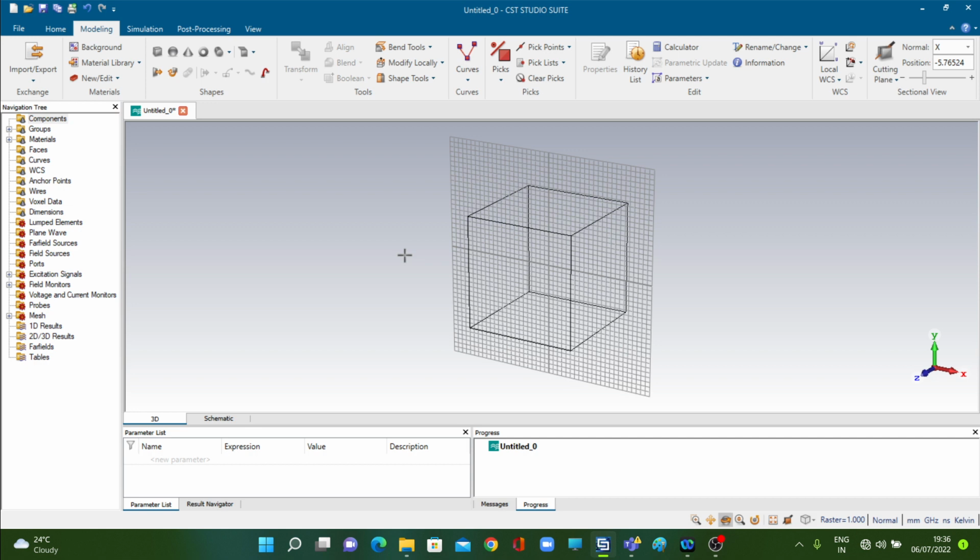The fifth part is designing and creating the waveguide port, which is nothing but the connector, that is, where the external coax cable will be connected to the actual feed line. That connection, that junction, is known as the waveguide port. So that is our final structure to be generated in the hierarchy.